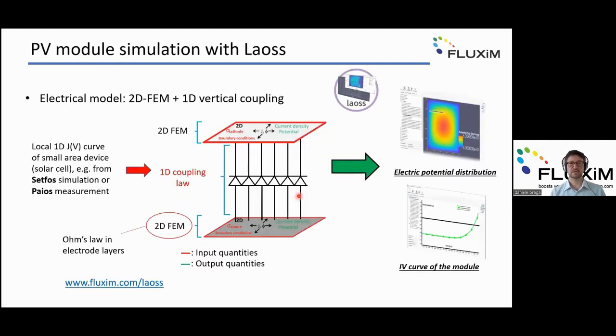We developed this tool called LAOS. It's a software based on finite element methods, a particular software using a 2D plus 1D approach. What does it mean? That we are resolving the distribution of the potential at the electrodes by using FEM, and the two electrodes are coupled by what is called a 1D coupling law.